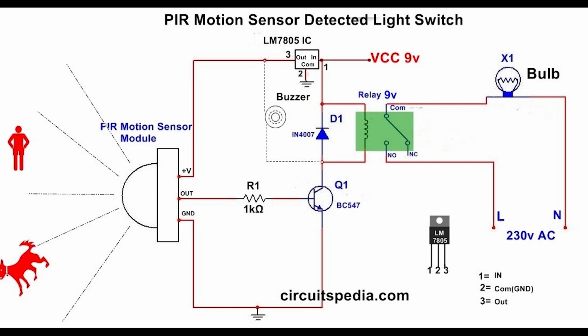If you're planning to direct the sensor without a module, that is the complicated thing. If you purchase a whole module, as I previously told, that is less complicated. It also has a 3-pin situation, because you can control the power pins and the output. For the detection zones, the Fresnel lens creates multiple detection zones.